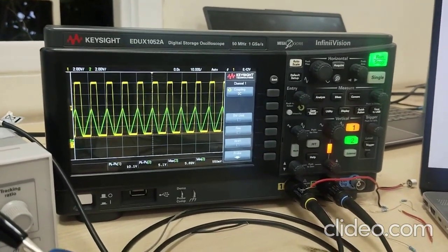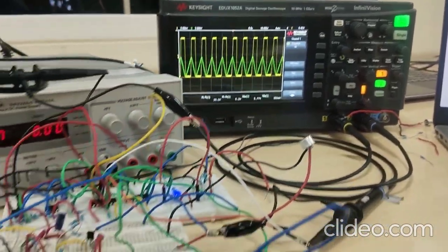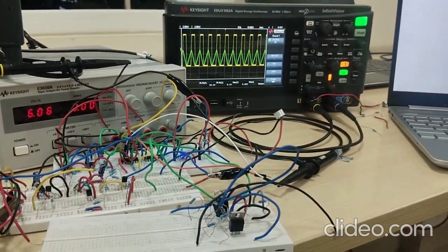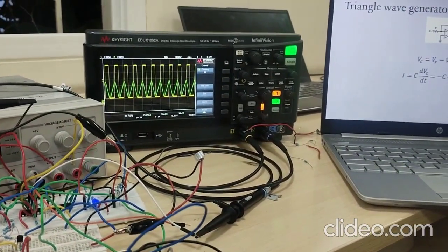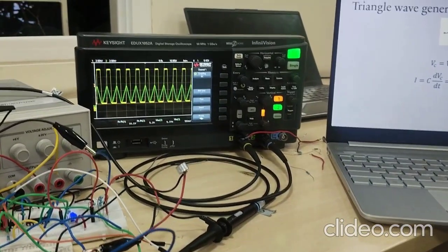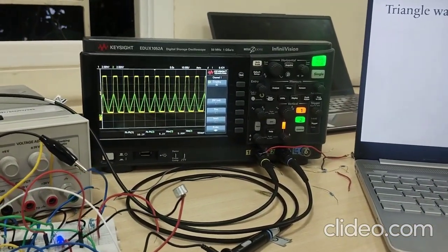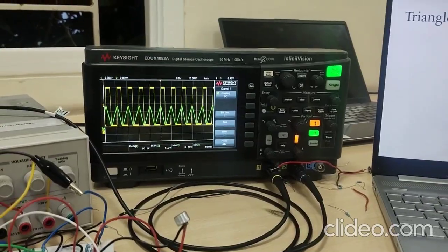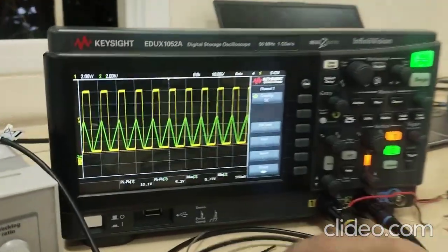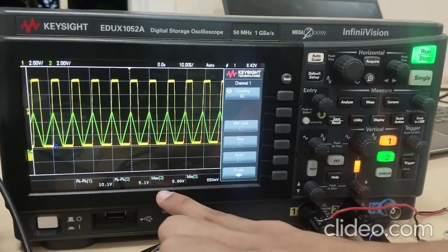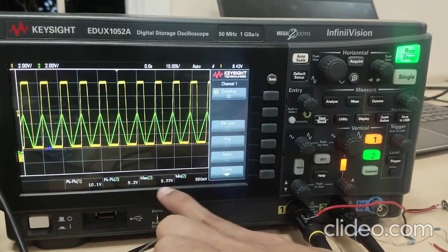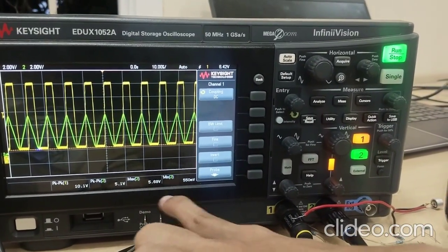Now we have designed our circuit for PWM modulation. The overall circuit is chosen so as to have high frequency, so that the carrier can accurately transmit the audio input signal. Here the triangle wave has a peak-to-peak voltage of 5 volts, and it is biased at 3 volts.